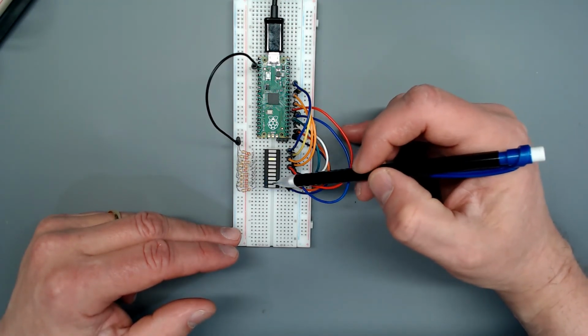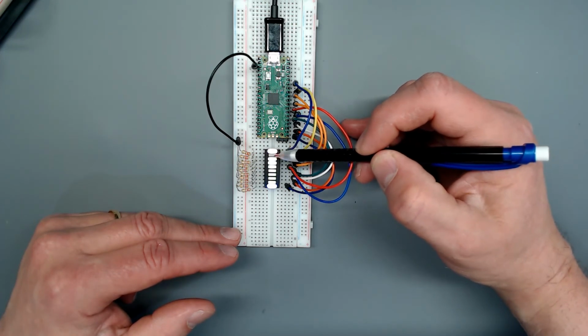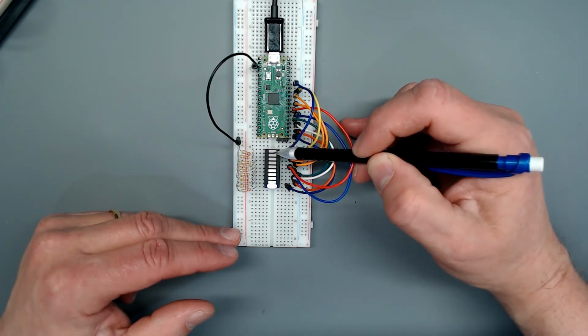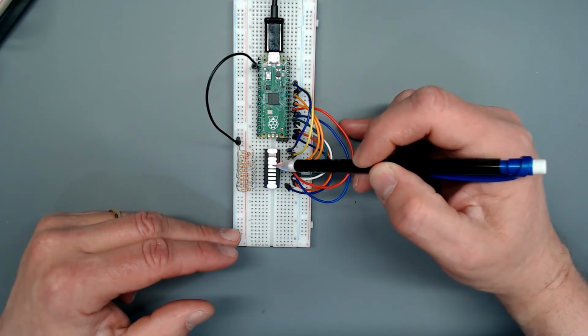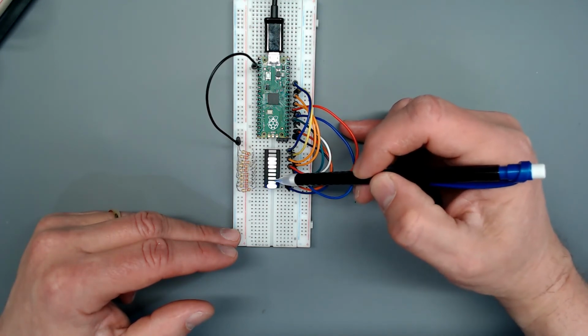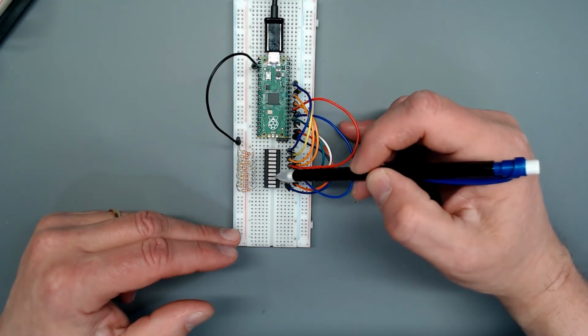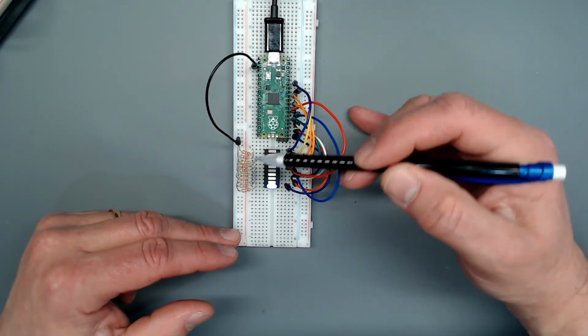But what I'm doing here is starting at the top, which is the J LED, and checking to see if our peak value is at that high. If it is, I'm going to turn that on. If not, I'm going to turn that LED off. And then do the same thing going downhill. That way, the lower values, which are commonly on all the time, stay persistent. They don't have to blink every time.